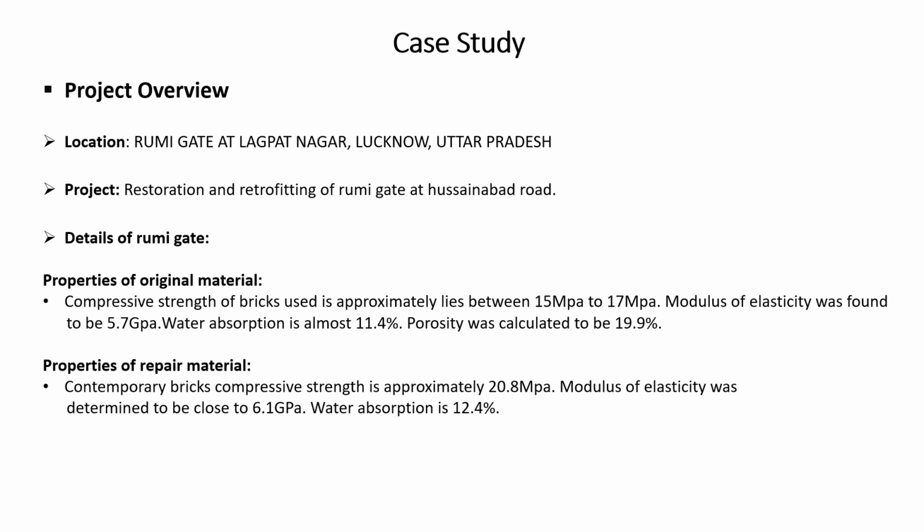Properties of repair material. Contemporary brick compressive strength is approximately 20.8 MPa. Modulus of elasticity was determined to be close to 6.1 GPa. Water absorption is 12.4%.